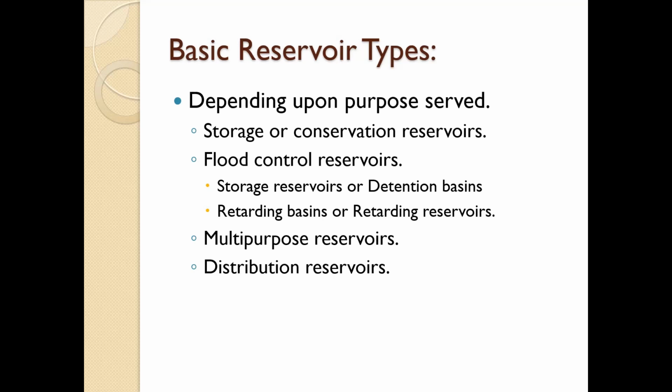Now the last type is the distribution reservoir. A distribution reservoir is a small storage reservoir constructed within a city water supply system. Such a reservoir can be filled by pumping water at certain rates and can be used to supply water at rates higher than the inflow rate during the periods of maximum demand, called critical periods of demand.